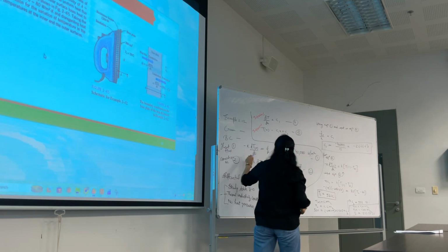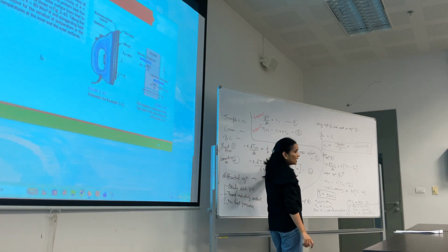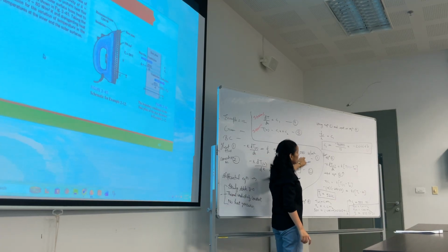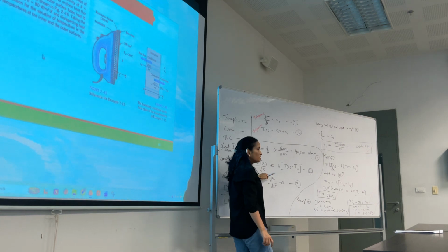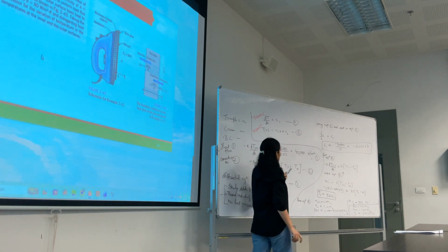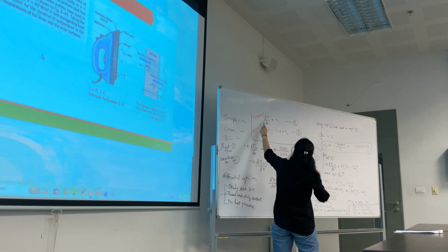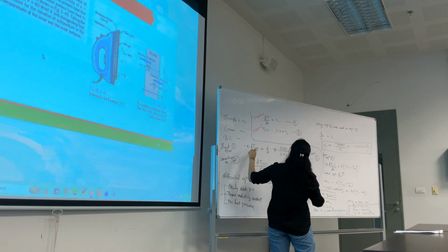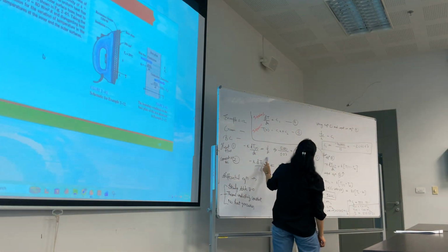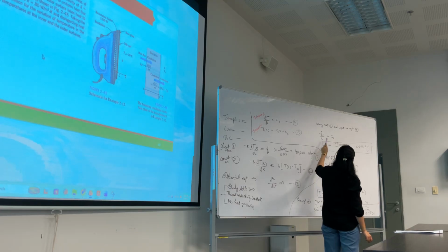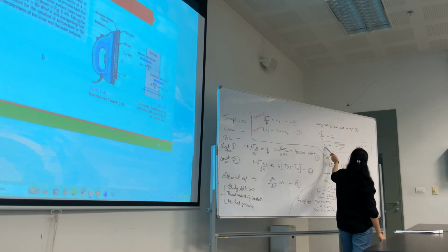From the question we know heat flux is heat transfer rate divided by the area, so we can find out the value of heat flux. The second boundary condition is the convection boundary condition: conduction is equal to convection. So we can input this boundary condition into this. dT over dx is q divided by k. Q divided by k equals C1. We know the value of Q and the value of k from the question, so we have the value of C1.